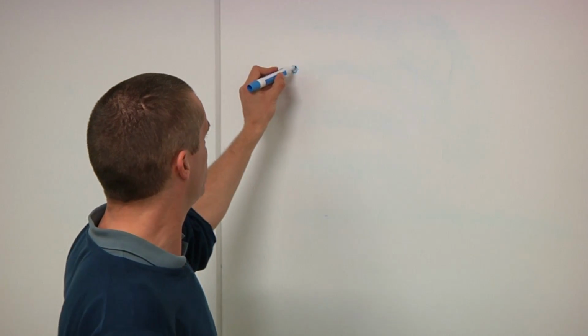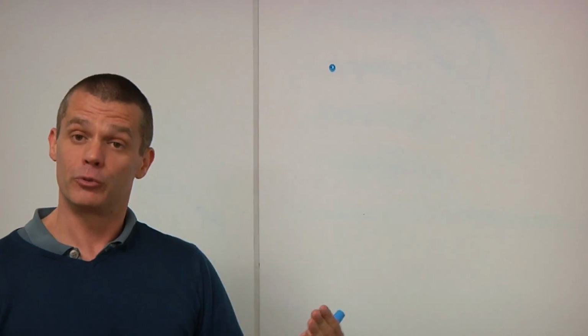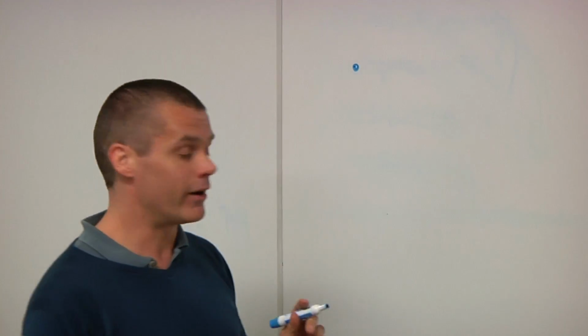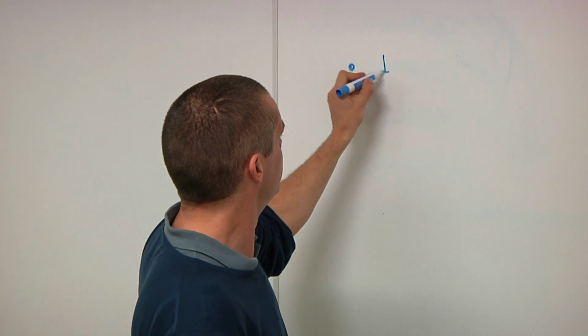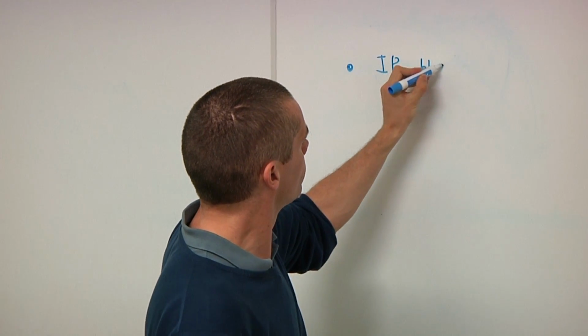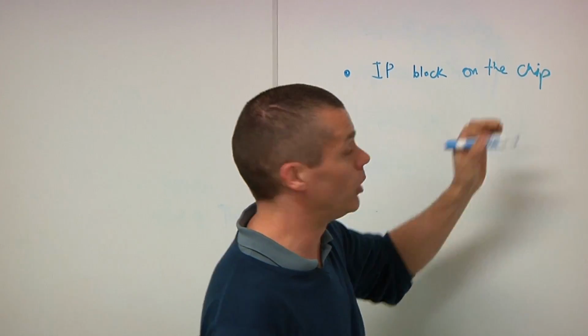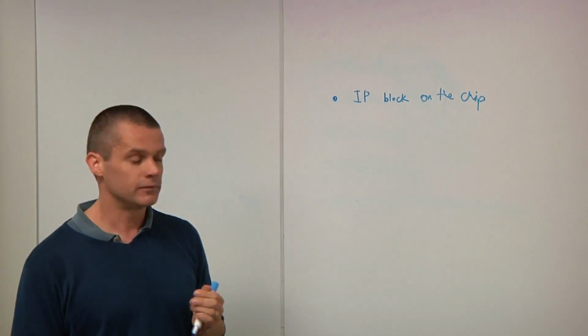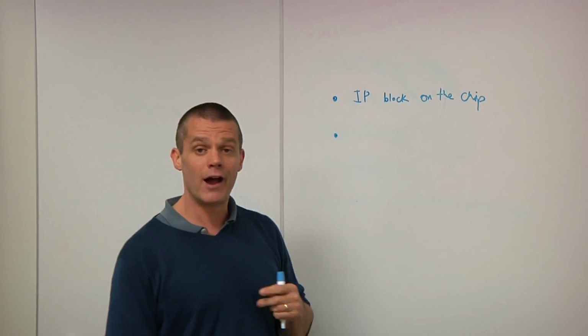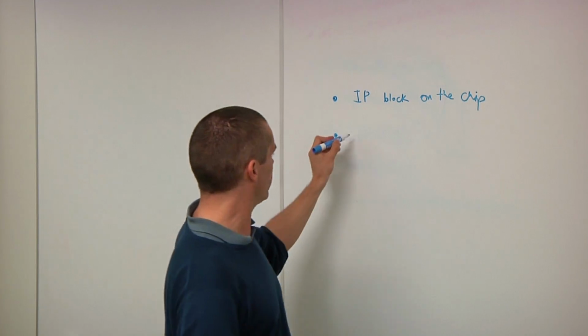So define integrated root of trust. What exactly is that from both a functional standpoint as well as how do you work with this in a design? Sure. Let's talk about what the main properties of an integrated root of trust are. First of all, what is it? It's really crucial to recognize that it's not just one thing, but a combination of primarily two aspects. The first is an IP block on the chip. And when I say the chip, in the case of mobile, typically I mean the applications processor. Alongside that, what you have is what we would call provisioning infrastructure.